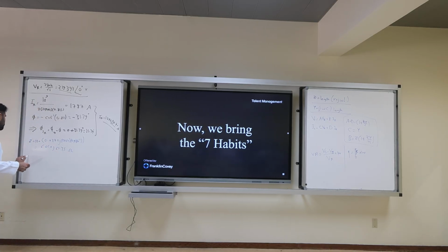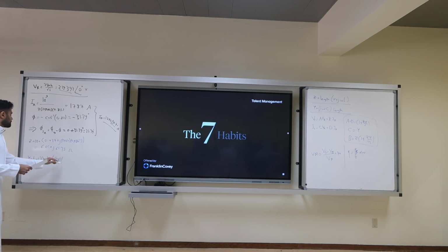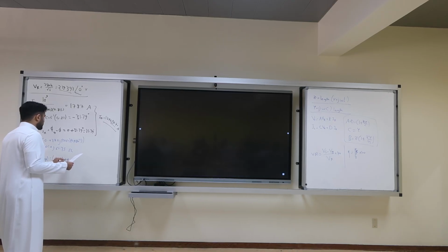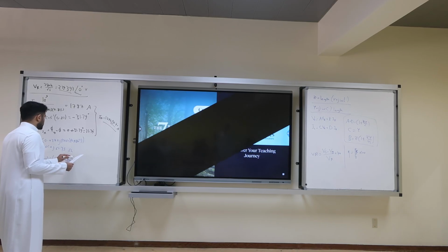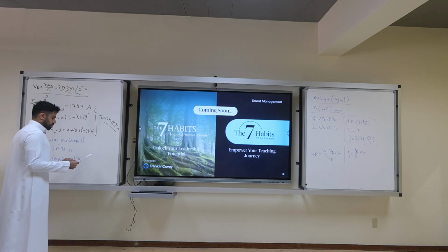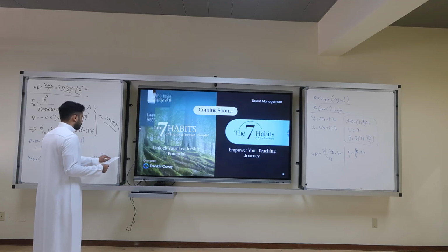And then what's Y? j omega C times the length, which is j times 2 pi 60 times C, which is 0.018 times 10 to minus 6 times 180, which is j times 1.22 times 10 to minus 3 mho.